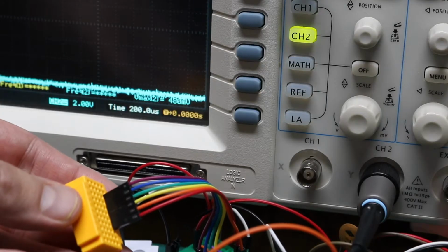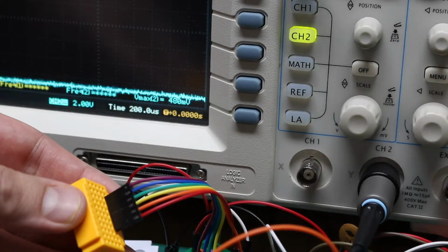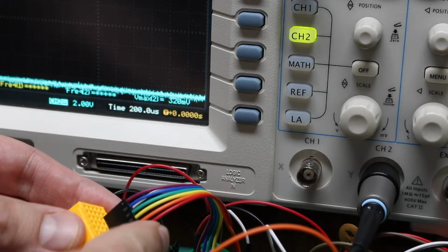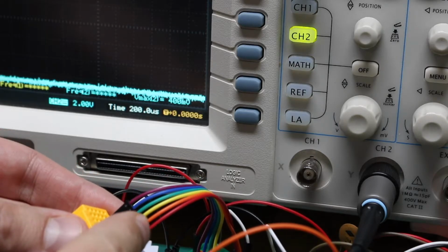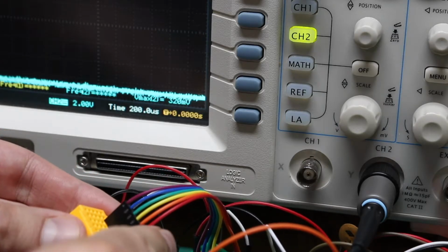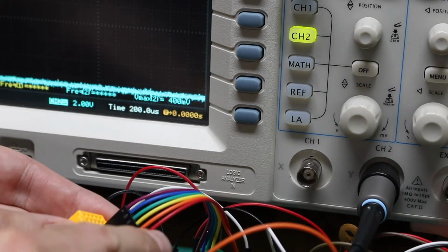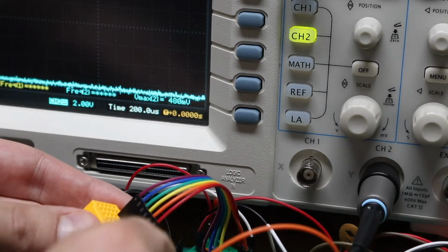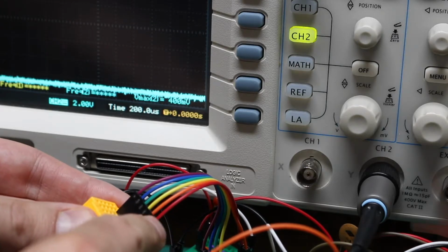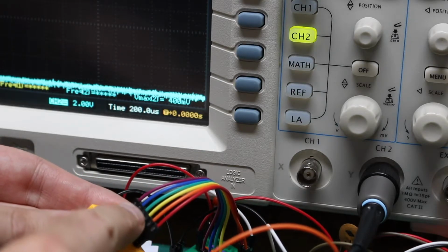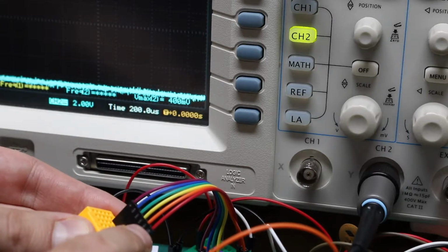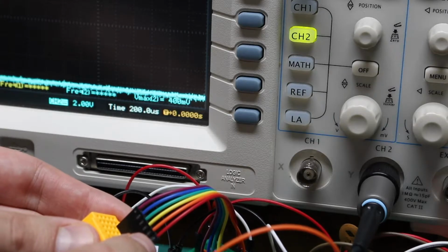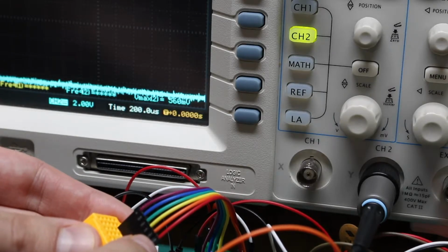So here I set the 555 to something about 5 kilohertz arbitrarily, and starting up here on the red wire and going downward, I've got the main 555 clock, and then the outputs of the 4040 ripple counter. So starting at 5 kilohertz, every time we go down through the ripple counter, we should be reducing the frequency in half, and that would correspond to an octave drop in the tone if we listened to it.